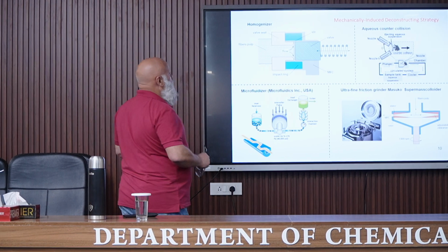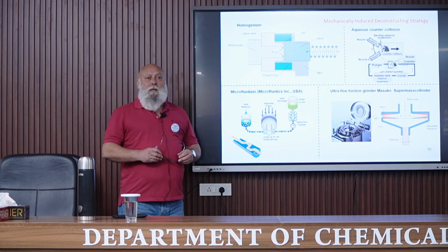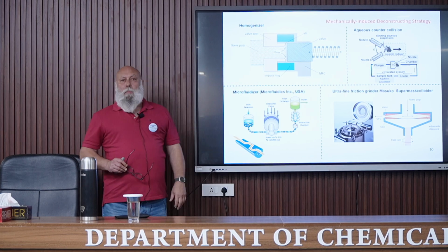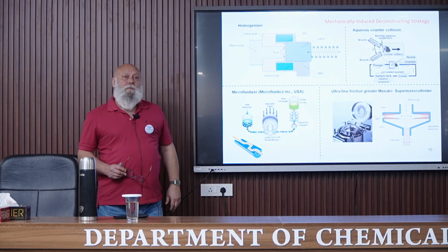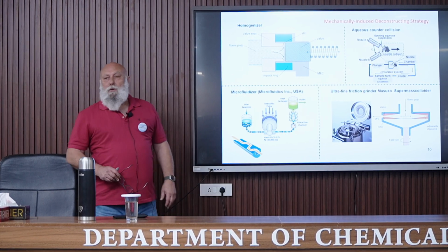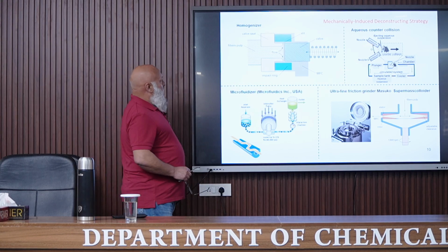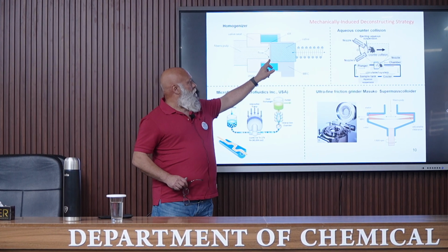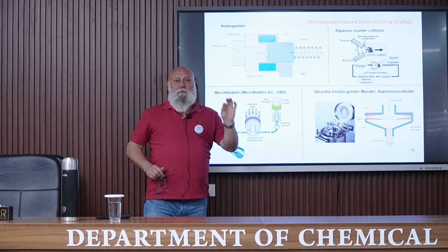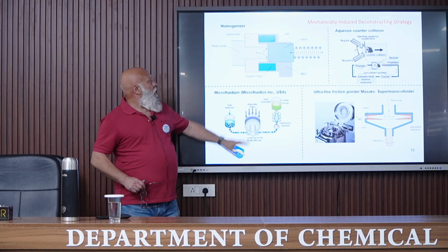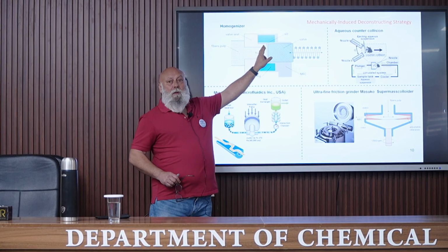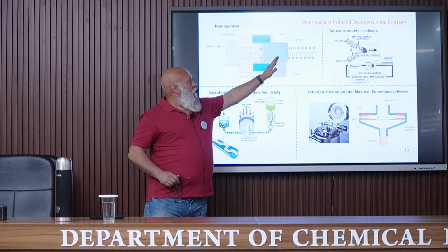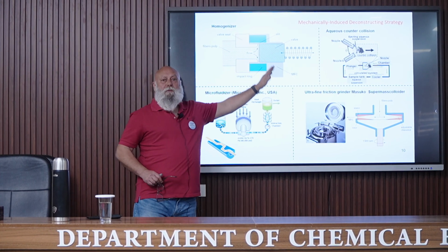It is the homogenizer, which is classically used in the food industry. So typically, a fiber pulp is used, a dilute fiber pulp. It's typically a 2% suspension, and this suspension is pumped and forced to pass through these very thin slits, and this gap, or the thickness of this gap, changes as a function of time because of the movement of this valve.